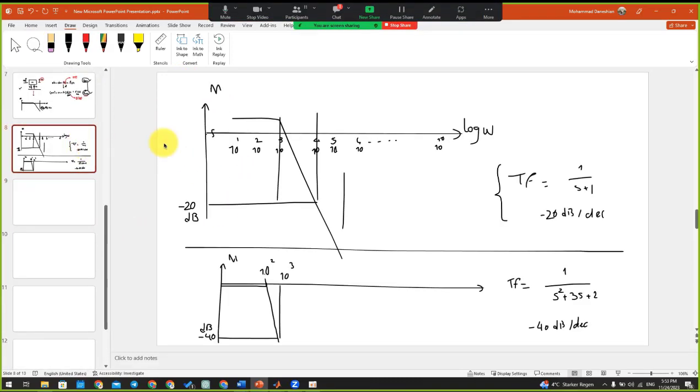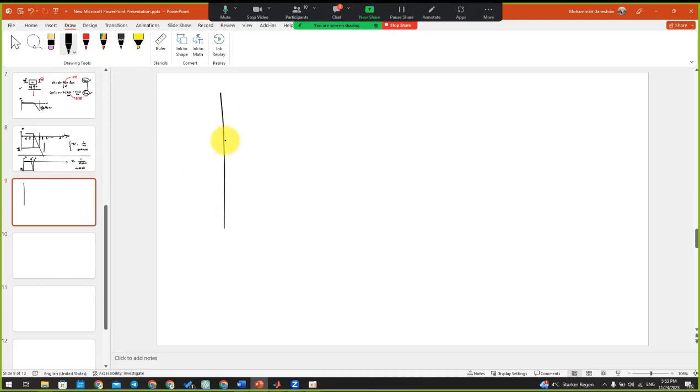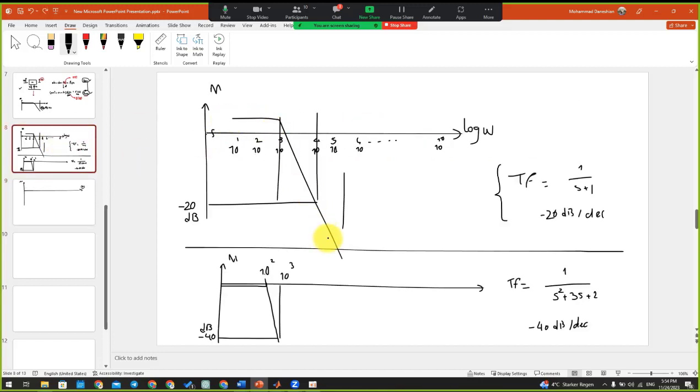Okay. So if we want to calculate the Bode diagram ourselves, here is magnitude, and here is the frequency, or the omega. So what we have to do is excite the system with all these frequencies, so we can see the magnitude. And this line that you are seeing here is not going to be continuous, and we have to calculate each point ourselves. But as I told you before, we don't have to do these calculations in linear scale, like 1, 2, 3, 4, 5 till 10, but